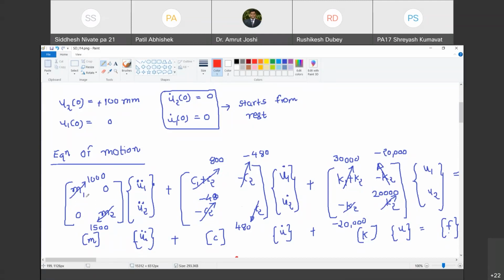And why is it feasible? Even in frame structures, you have a wall, but that wall is not considered as a structural element. Its mass or its weight is transferred to the beam below, and that means it is transferred to the floor. Are you with me? Yes, sir. So whenever we consider the total mass of the structure, we take into account the mass of the wall and we lump it to the floor on which that wall is resting. Happy? Yeah. Okay. So we will look at those practical details a little later, but I just gave you a glimpse.